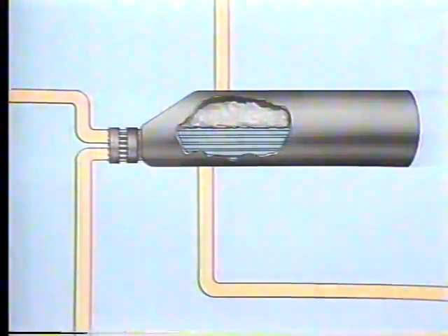In this example, the controlled variable is the pressure of the steam at the output of the heat exchanger. The steam pressure is maintained by two variables: the steam flow through the tubes and the level of water in the shell.